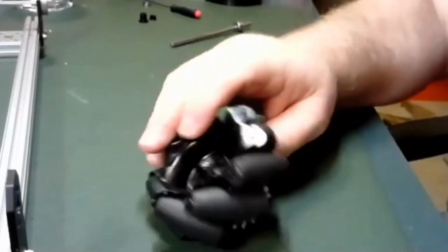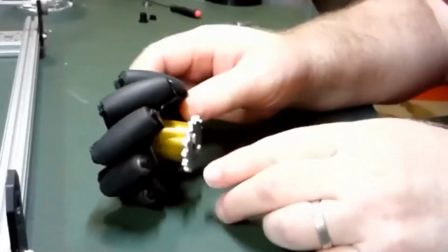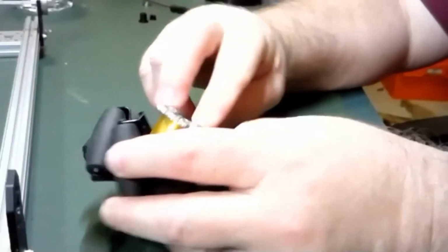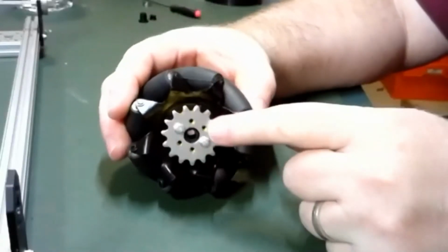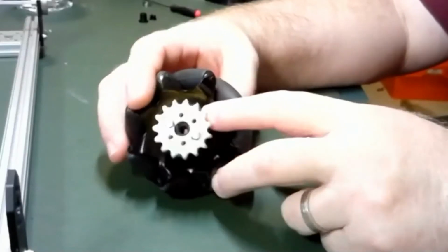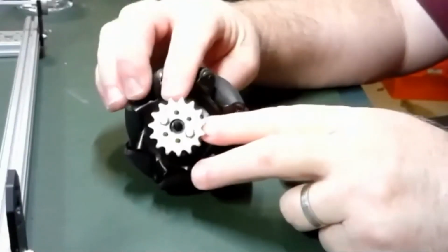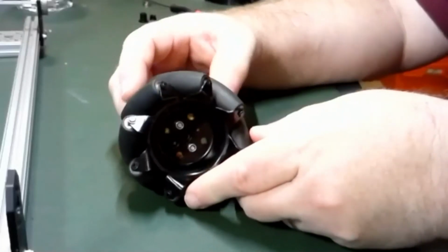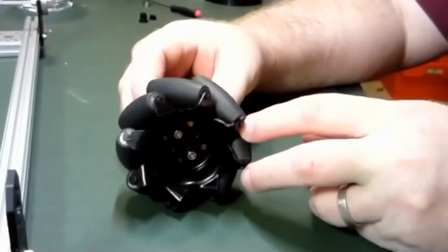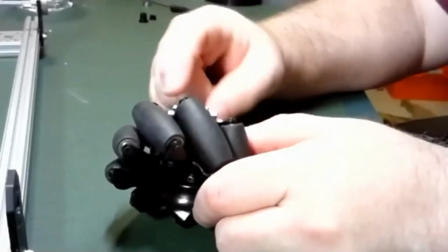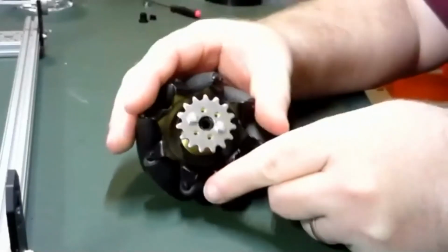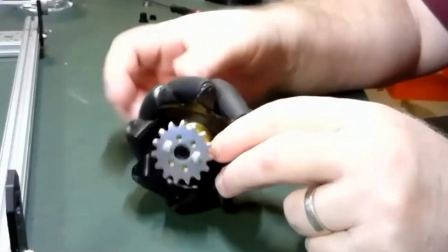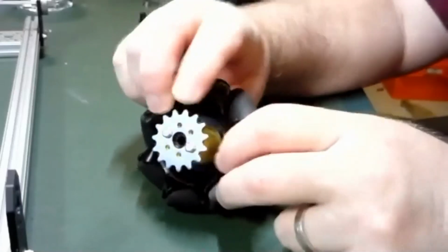view of my wheels here, you'll see that the way this is done is there's a pair of screws that go in through the sprocket into the 3D printed piece. Those screws actually go all the way through the printed piece to the other side, where they're attached with nuts. So it's not as if the sprocket is attached to the 3D printed piece and then the 3D printed piece is attached to the wheel. The sprocket and the wheel are connected by the screws.